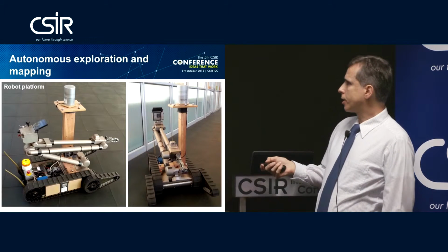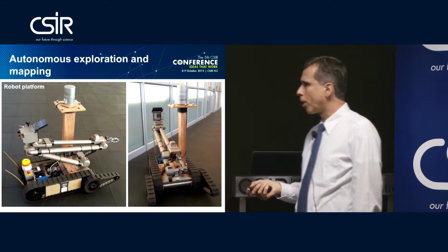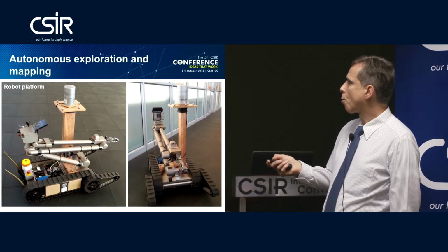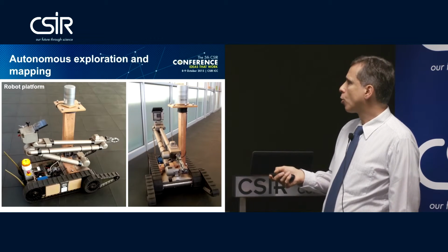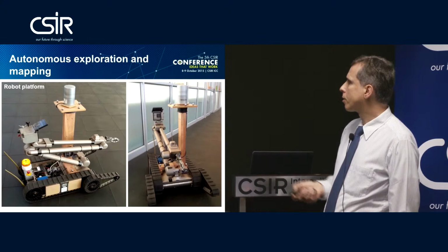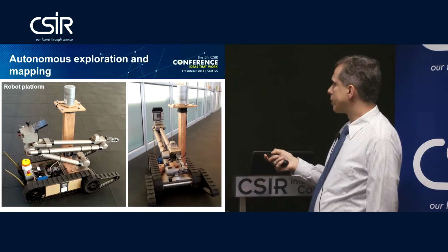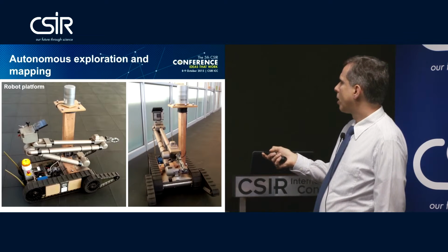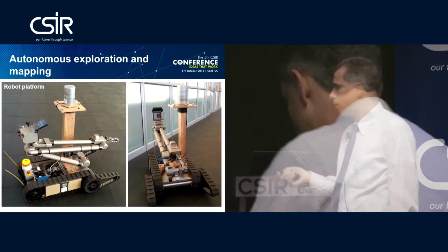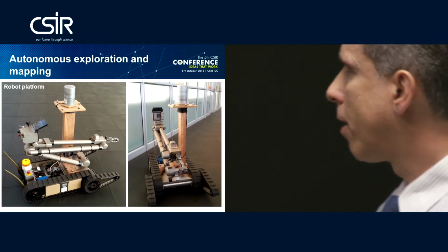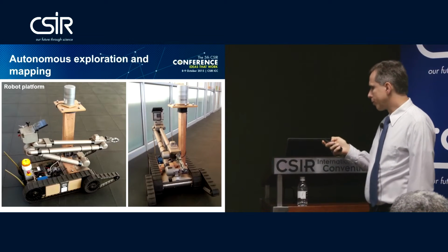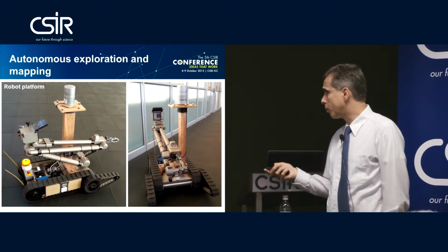The robot platform in this case is a PackBot 510, which is manufactured by iRobot Corporation of USA. We have put a sensor mounted here, and in the payload bay we have a computer. Here's the sensor, there's a wire which carries the information down to the computer, and that's our computer vision system. If you look at the front of this, we see some cameras. There's a head cam here and another camera down lower. There are more on this platform, but we have one on the head cam here and one a little bit down below, and those are used for feedback to an operator.